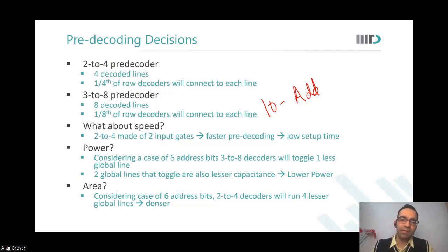If the maximum NAND gate stack has to be 4, how many maximum pre-decoders can you have, if you want to do single stage post decoding? However many bits you have originally doesn't matter. How many pre-decoding groups can you have if you have 4 input NAND gates at the post decoding? If my final NAND gate can accept 4 inputs, how many pre-decoders can I have?